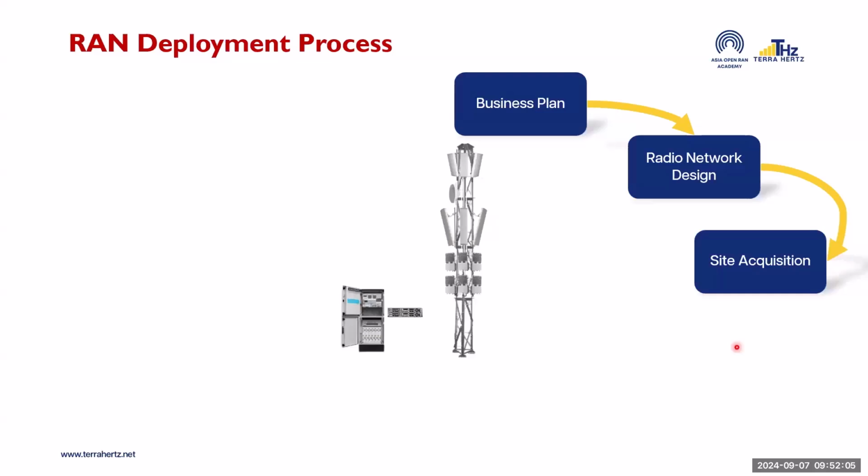Okay. So after we finalize that area, so nakausap na yung may-ari ng lupa, okay, so dito na itatayo yung cell site. So we finalize the coordinates, we finalize the tower height, the tower structure. So we go to site engineering. So this is the time where we prepare the bill of quantity or bill of materials, no? Okay. So how many antennas are needed, how many radios are needed, what type of tower is needed, how many microwave antennas are needed, okay, what power supply is needed on that area. So that is part of the site engineering.